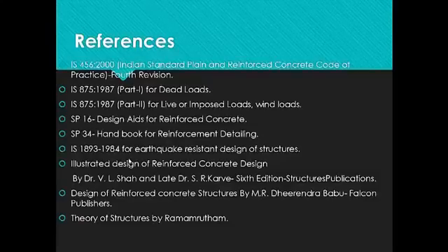The references for my project are IS 456-2000 Indian codes, IS 875-1987 Part 1 for the dead loads, IS 875-1987 Part 2 for the live loads and wind loads, SP16 design aids for reinforced concrete, SP34 handbook for reinforcement detailing, IS 1893-1984 for the earthquake resistant design of structures, Illustrated Design of Reinforced Concrete by V.L. Shah and late Dr. S.R. Karve, Design of Reinforced Concrete Structures by Mr. Dhirendra Babu, and Theory of Structures by Ramamrutham.